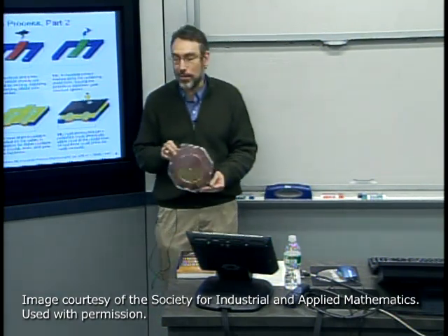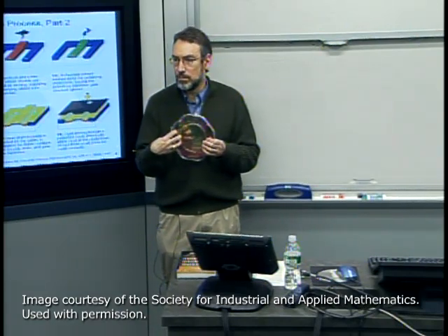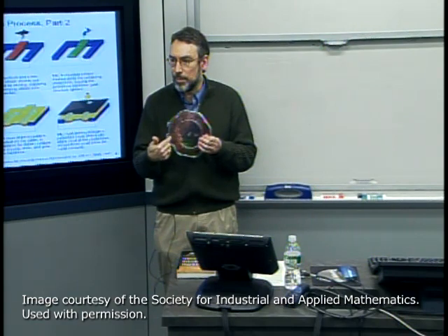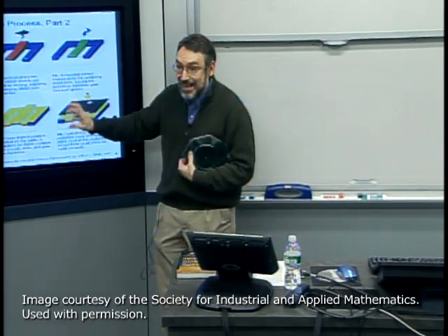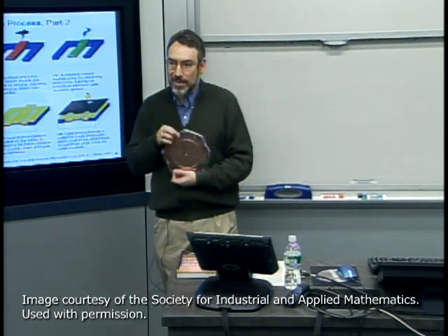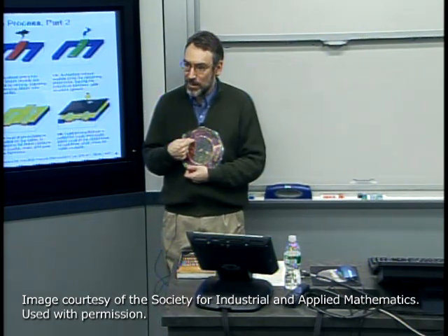So in fact, the photolithography equipment is typically called now a stepper because it's imaging one field, maybe one chip. There may be more than one chip in each field, but I'm stepping through in order to get the control and be able to achieve the alignment on one chip at a time. And in the most modern equipment, in fact, they don't even image the whole chip at one time.